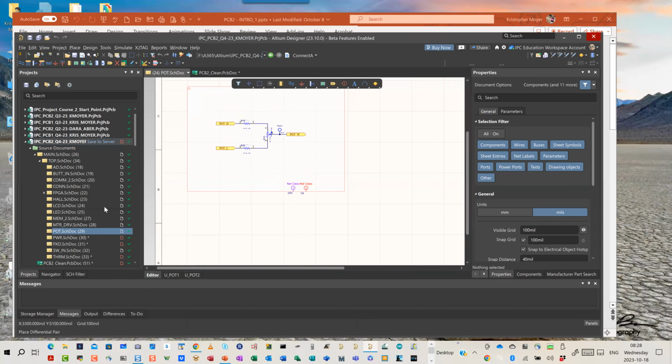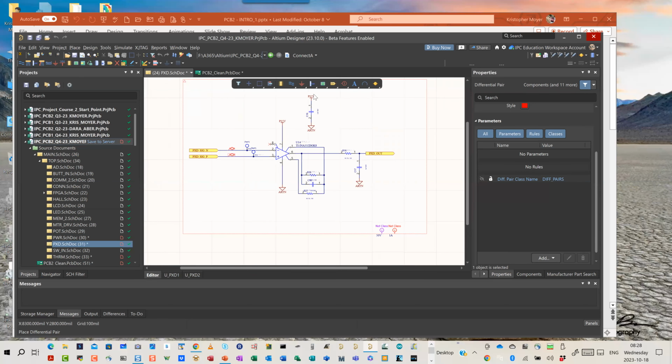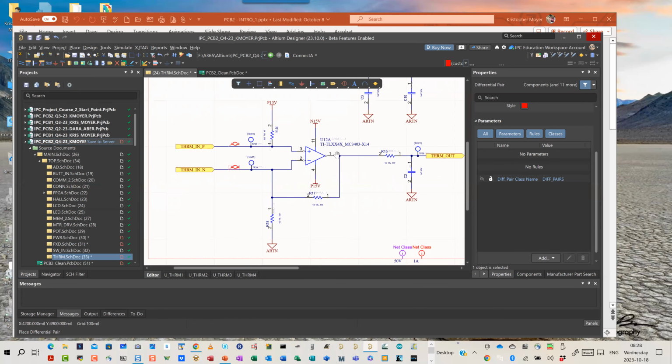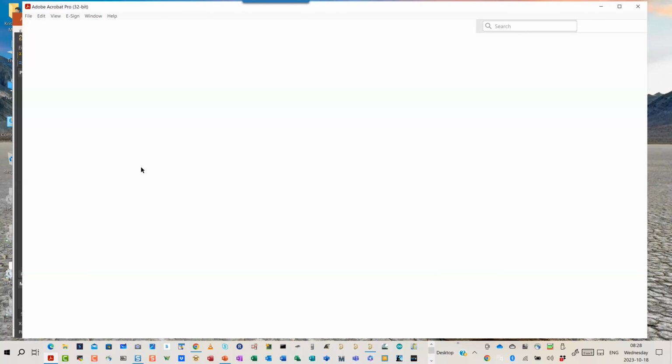Now, we'll notice, however, that, well, this is not a good example. Let me look at the pressure transducer I was just in. Pressure transducer here, it's plus 15 volts for its power supply. My thermistor is plus and minus 15 volts, right? So I'm nowhere near my 50 volt rating. Here my op amp for my thermistor is plus and minus 15 volts, and so on and so forth. So I have it all at much lower voltages, but I have it all rated as 50 volts. And the question is why? Why do I have it rated that way?